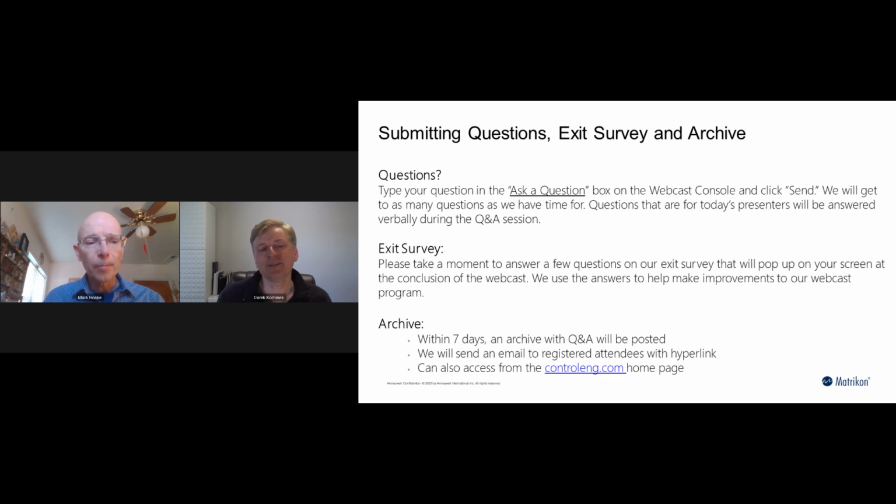Number one, the convincing side, as far as the merits of securely accessing data. Number one, there's the fact that it's OPC UA based. That addresses certain fundamental questions of, is the data encrypted, protected so others can't look at it, is the trust established between different components, etc. Now, building on top of that, if, for example, you're using things like reverse connect, then you're maintaining control of who gets to connect if it's going to come in from the outside.